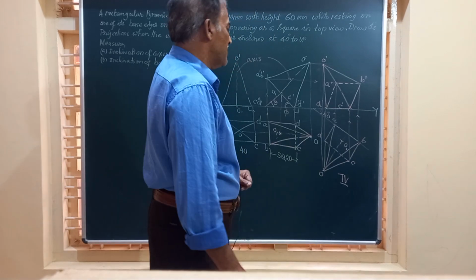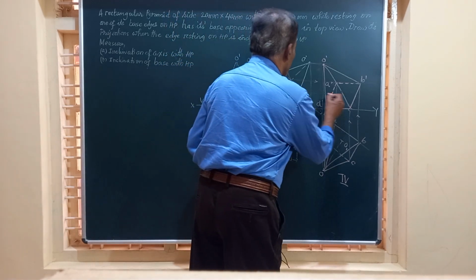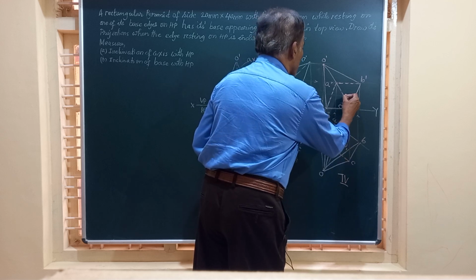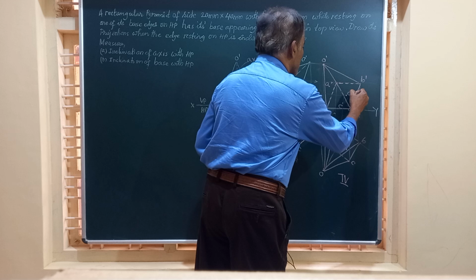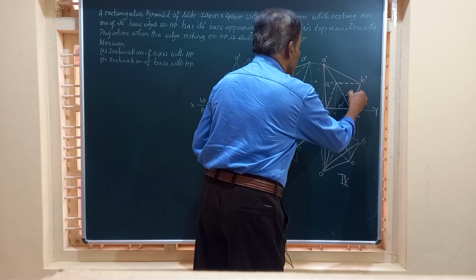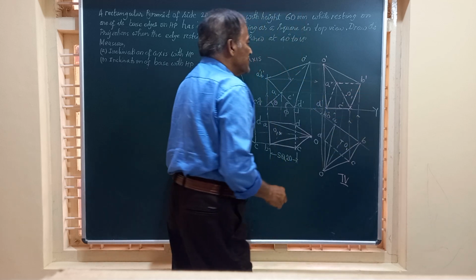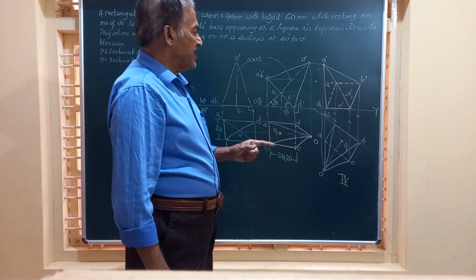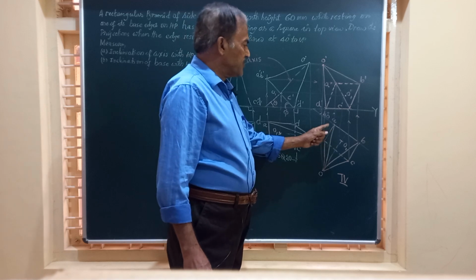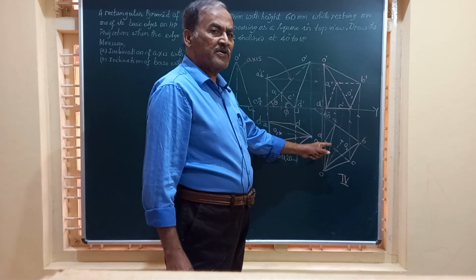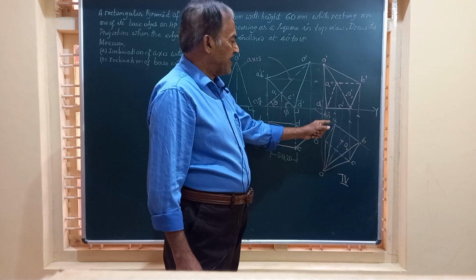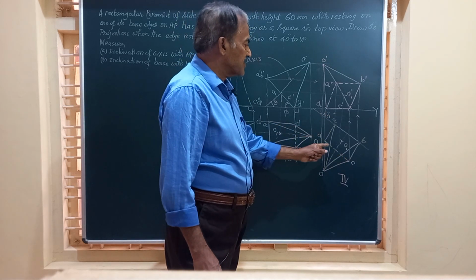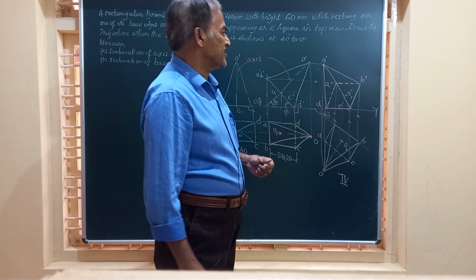Friends, you can observe here, we have this axis somewhere here. So we are going to join that there. So this is O double dash or O1 dash we can say. Friends, this is how the front view of this solid looks when the shorter edge AB of the pyramid is making an angle of 40 degrees to VP, or this DC or CD is at an angle of 40 degrees to VP.